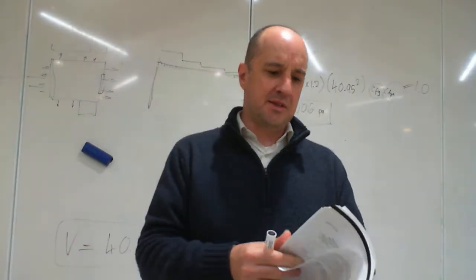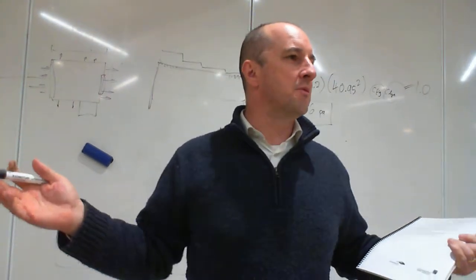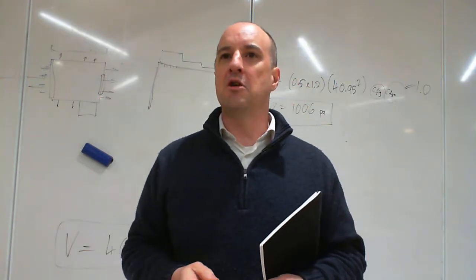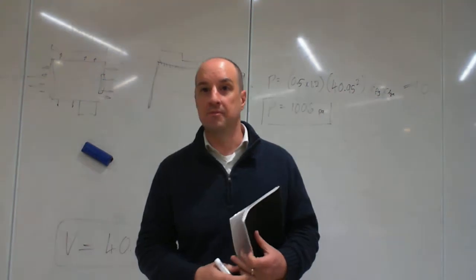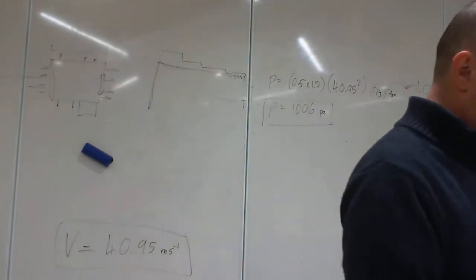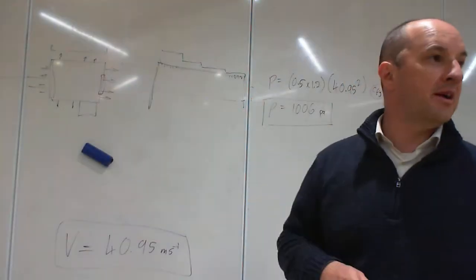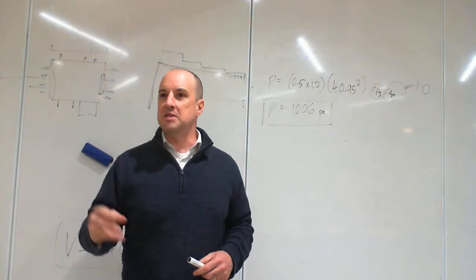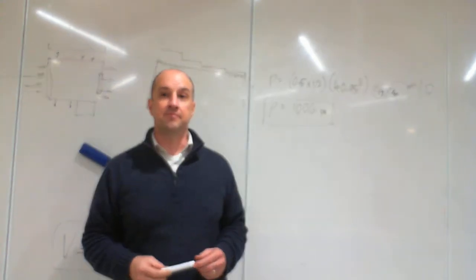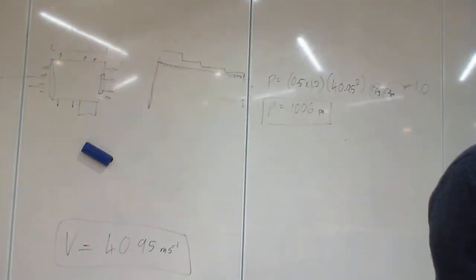That's basically assuming that in a big windstorm, the wind is transient, and when the major gust hits, it doesn't hit the whole large building all at once. I should backtrack and say the wind speed we're talking about in that V, I think, is a 3-second gust. So it's the maximum wind speed that will be sustained for 3 seconds. And that's the definition of that. Correct me if I'm wrong on that, but I think that's right.